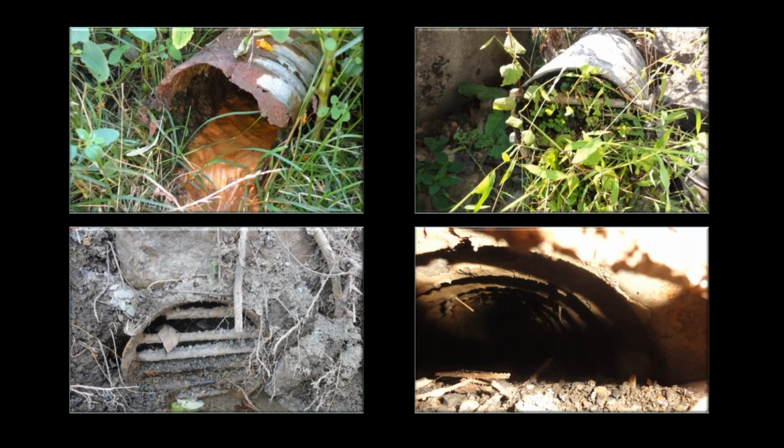And in this particular inspection, as the video was made, as he went near the core of the dam, the conduit actually did have a sag in it, and that's why there was water, as well as a little bit of a leak in the gate. So those kinds of inspections can be done even under those conditions. Just a matter of adjusting the wheel height or the wheels on the ROV.